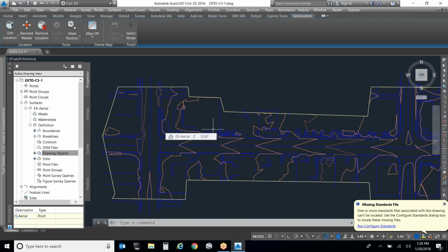In addition to that, when they do a dip or an invert elevation, they will draw a sketch of the manhole or the storm drain, okay, and show you what elevation is coming in, in which direction, and the size of the pipe. Okay, they'll have an 8-inch clay pipe and a 10-inch PVC and a 12-inch PVC going out.